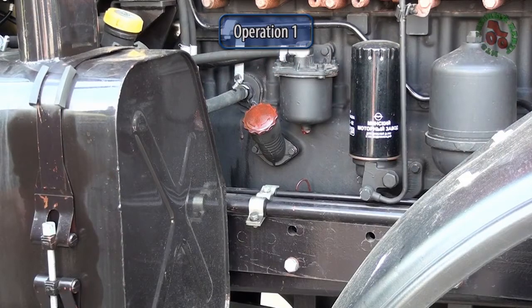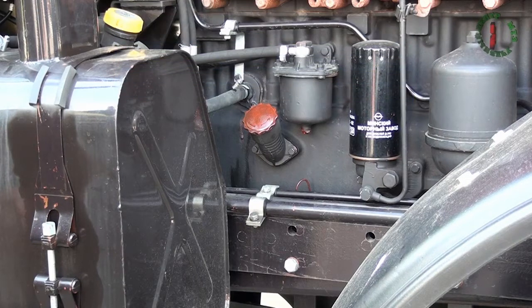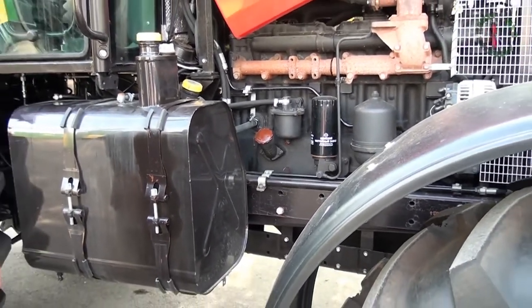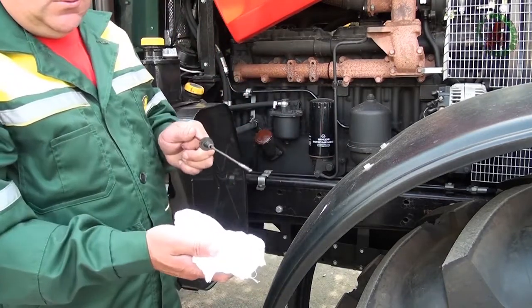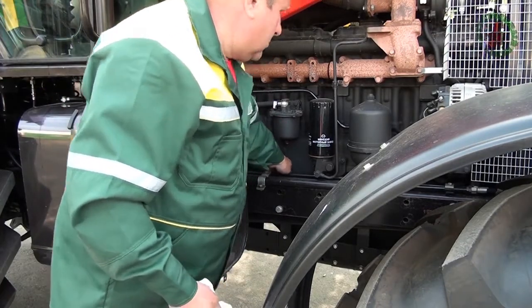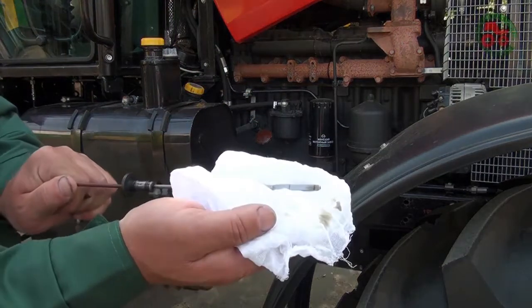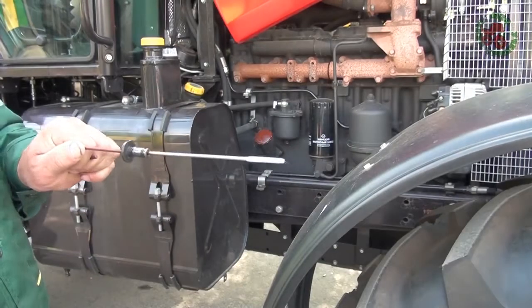Operation 1. Check of oil level in the engine. Set the tractor on a flat horizontal surface. Check the oil level in the engine no earlier than 3-5 minutes after engine stop. When oil flows down in the crankcase, pull out the probe, wipe it with a clean cloth and put the probe back until it stops. Pull out the probe again and inspect the oil level. It shall be between the highest and the lowest marks of the probe. If necessary, remove the cap and add oil through the filler neck.